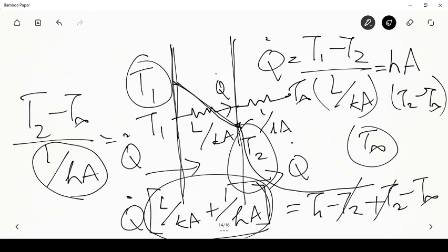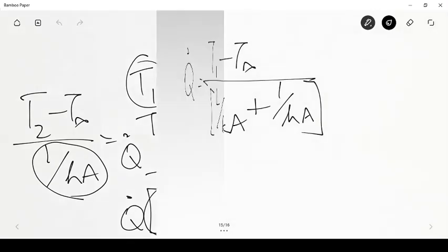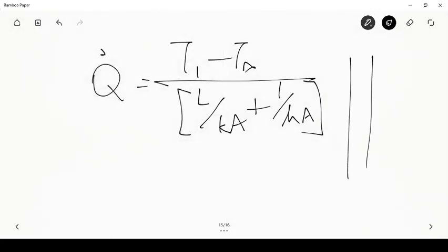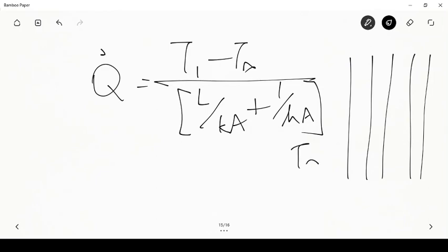This can further be extended also. Suppose I have a multi-layered wall. So let us say this kind of wall is commonly encountered, for example, in furnaces, where suppose this is the highest temperature, let's say Tg, where the gases are there, and from the gases there is a certain temperature gradient to the inner surface of the wall, and after that there is the refractory wall, the brick wall that is inside, and then on the outside of it there might be air gaps, there might be various commercial insulations, and there may be a metal cladding that's on the outside.